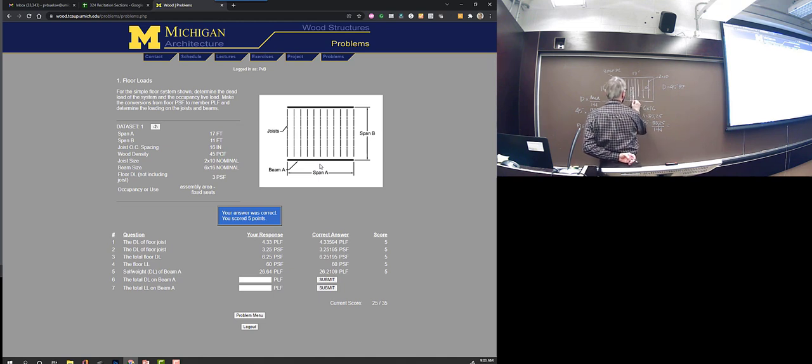And finding the weight of it. So the depth of it here is 5.5 feet, and the width is 1 foot wide, so the area is 5.5, and the weight in PSF we said was 6.25, right? So it's 5.5 square feet times 6.25 pounds per square foot. So that should give me the weight of that.